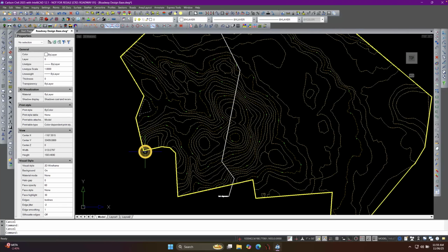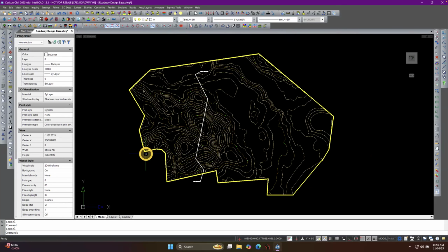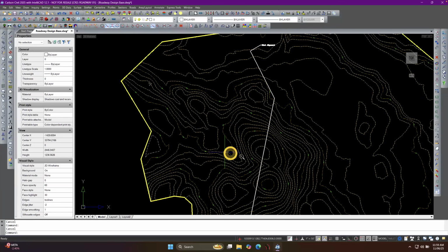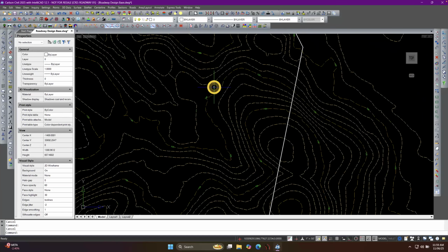All right. So we've got our mapping ability to create that from the surface. So let's go back now because I've changed my scale and I want to change that interval from every 250 feet to, let's make it every 750 maybe. There's 250, 500, yeah, every 750. So what would you do? There's a number of things you can do.